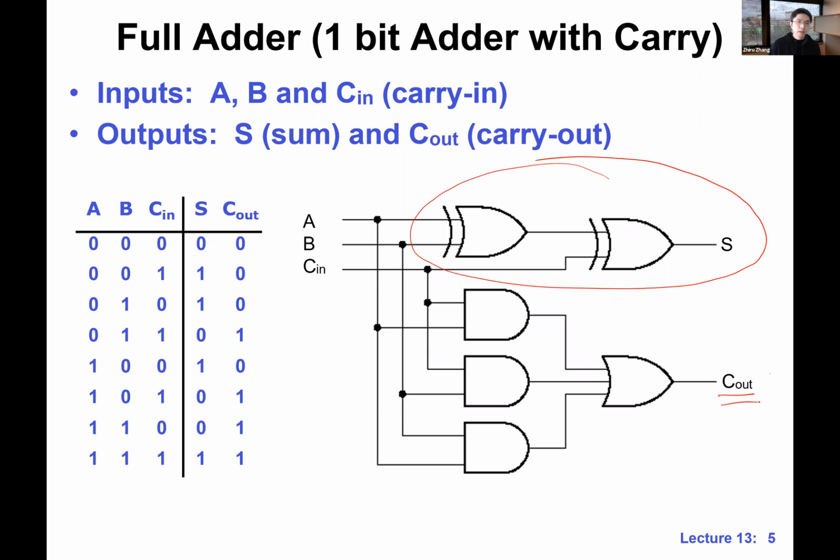Also, later on, we're going to be analyzing the delay for these kinds of adder circuits. So here's my assumption. Let's say each gate takes 1 nanosecond. All of these gates. What is the longest path here? Later on, we'll just call it the critical path. By critical path, I mean the longest propagation delay. It's obvious here. The longest one is just 2, because we're going through 2 levels.